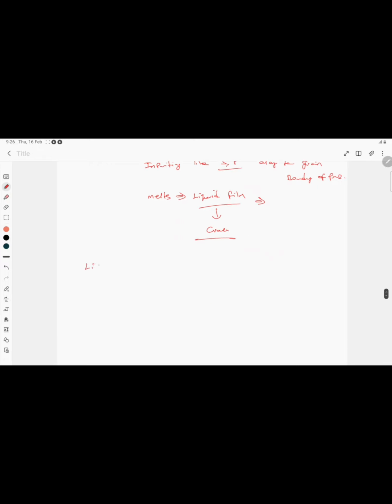And whether it is possible for this liquation crack to occur in the fusion zone of the weld, it is possible only in multi-pass welds. In multi-pass welds, the same phenomena which we have discussed before may happen. Since we join thicker plates by multiple passes, in those kinds of welds there is a possibility for the liquation crack to occur even in the fusion zone of the weld. But if it is a single pass weld, it will only occur in the partially melted zone of the weld.